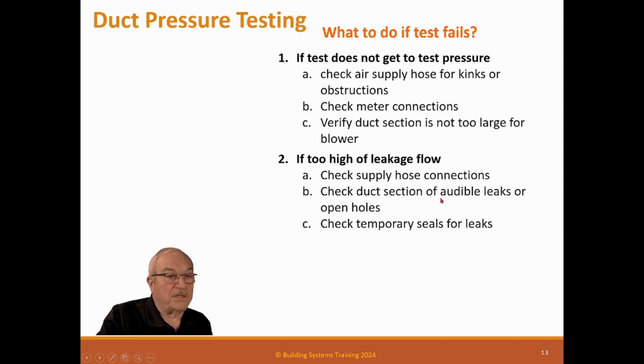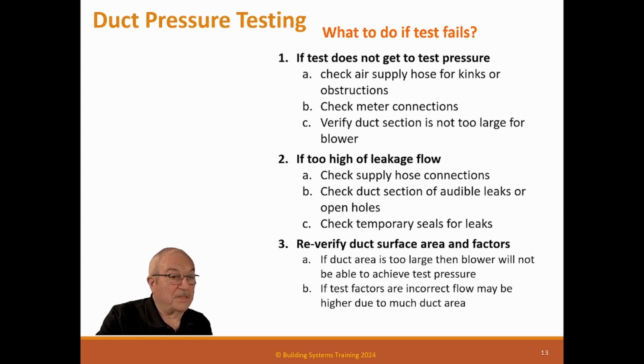Check the duct section for audible leaks or open holes. And normally you can do that. If you get close enough, you can hear the duct leaking as long as you're not right next to the blower. And check temporary seals for leaks, because a lot of times your leakage is at your seals. And obviously we don't want that failing a test, so you have to reseal it. So if you find a leak, then we need to seal it and then redo the test.